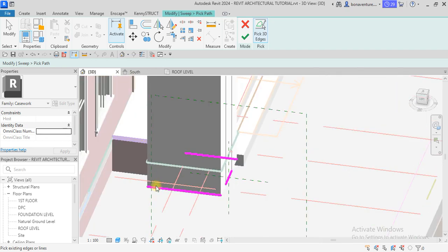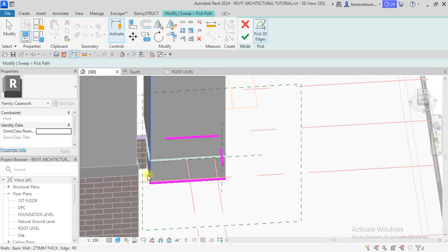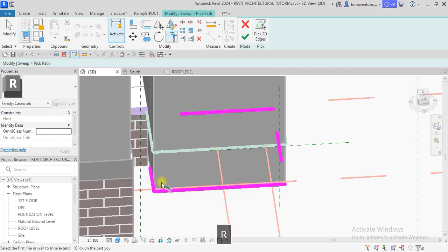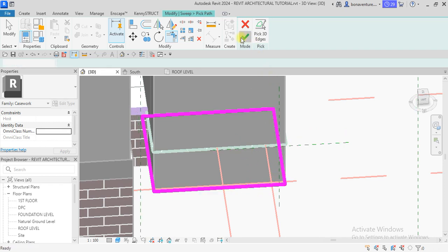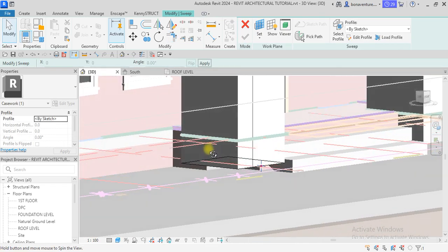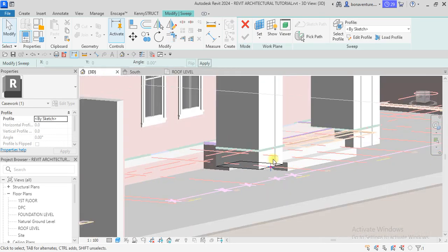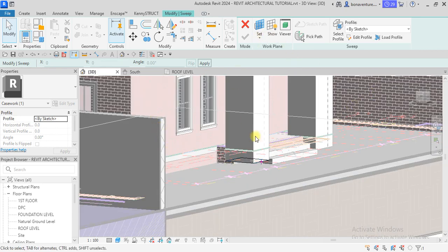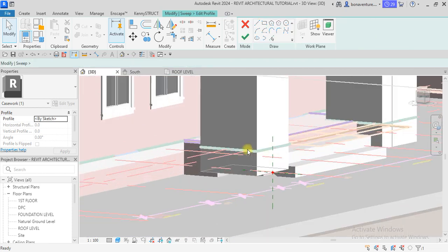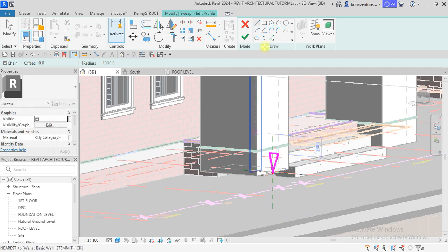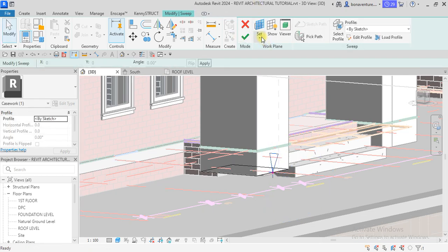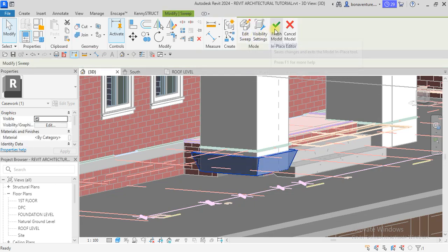So for the third side, how do I now select it? Okay, I think to go this way, so I'll say trim. Okay, so having done this, I say okay. Now I have an issue with this wall, it's just obstructing. So what I'll do, let me edit profile, let me just do a small thing so I can go and remove the wall. Finish model.